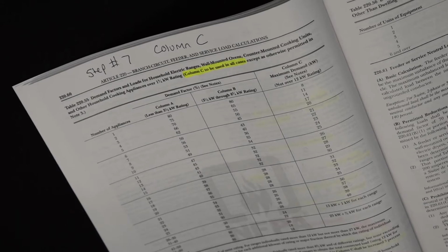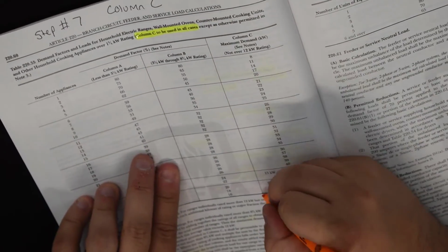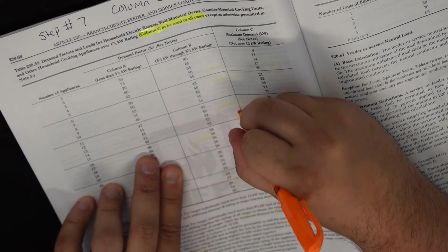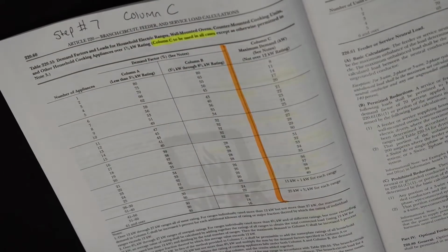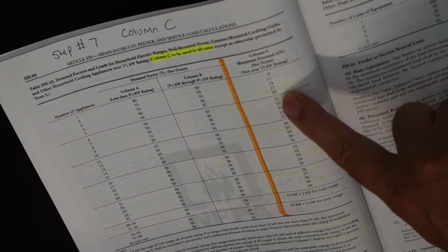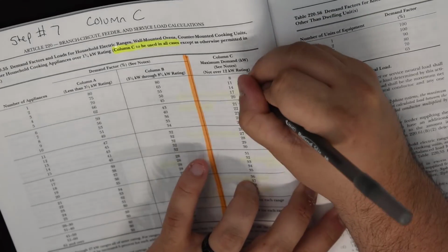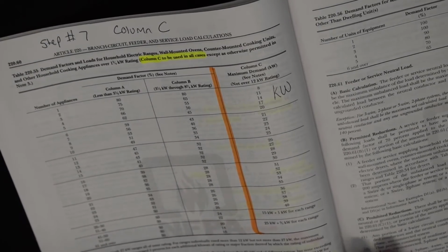So take the dark color highlighter and we're going to segregate this line here to make column C kind of stand alone. We're also going to take our pen and over here where it's got the numbers 8, 11, 14, 17, 20 and write kW there. Because kW stands for kilowatts, that means 1,000 watts. So 8 there represents 8,000 watts, 11,000 watts. Now we're going to go ahead and talk about note number 1 down at the bottom. The reason why we're going to talk about note number 1 is because if you look at column C, it says maximum demand kW. It says C notes if we've got problems here.